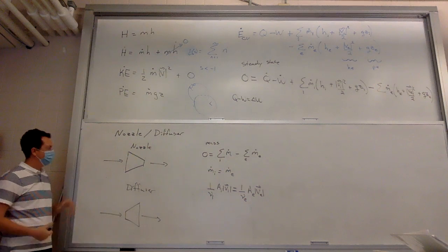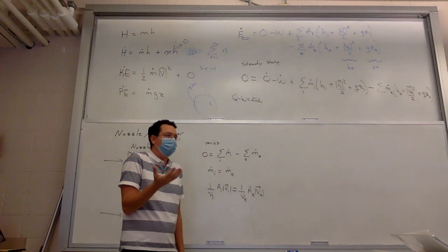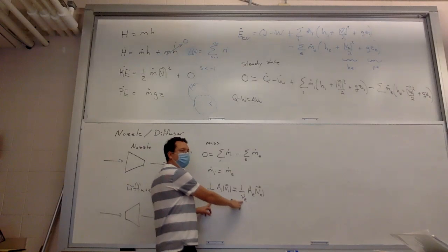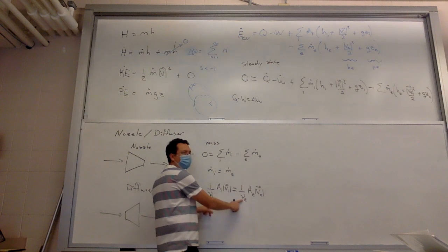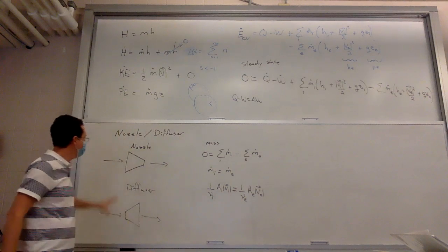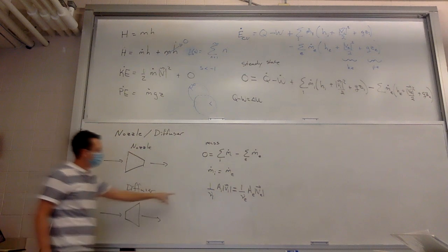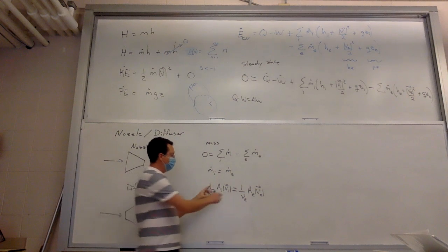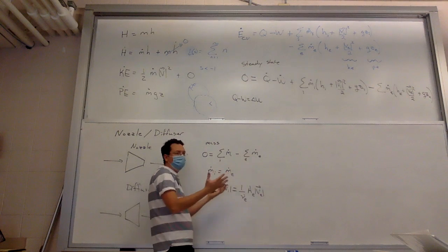Now, if I'm thinking about water through a garden hose, the density doesn't really change much. Yes, there is specific volume stuff happening, but for our intuitions anyway, we're going to assume that these don't dominate the effect. That tends to be a good assumption. So now, tell me what's happening. What's shrinking here? What does that change in this equation? Area. It changes the area first, and so if I shrink the exit area, then the rest of the variables have to adjust.